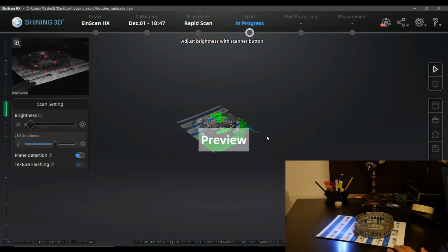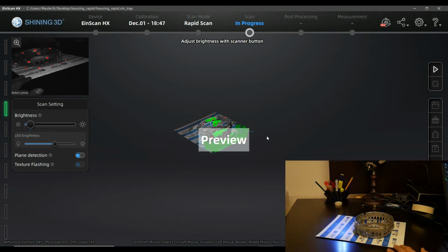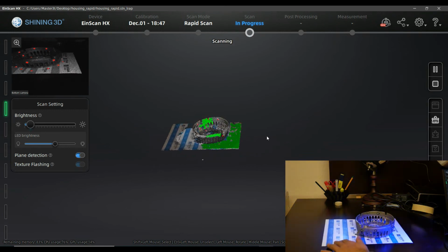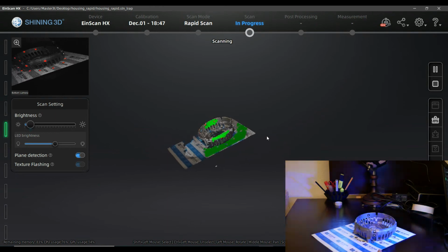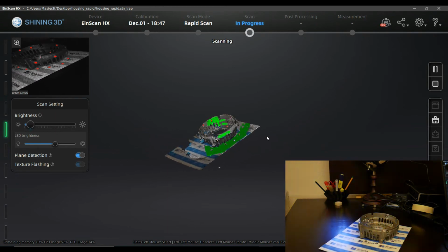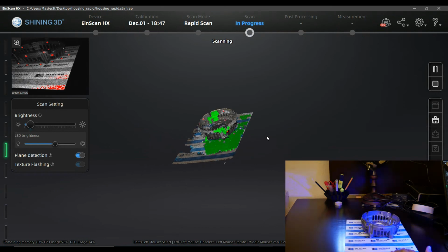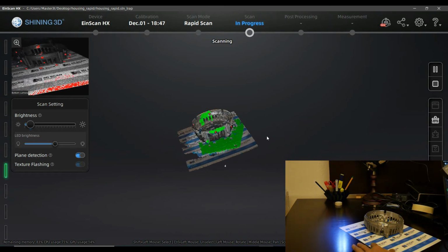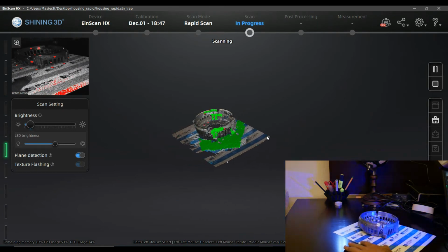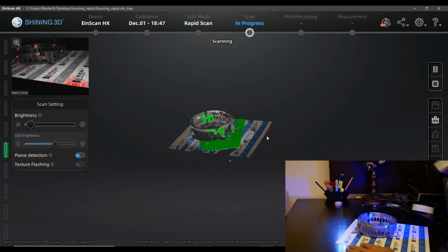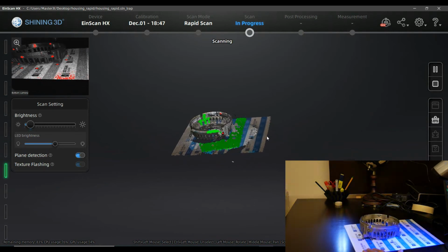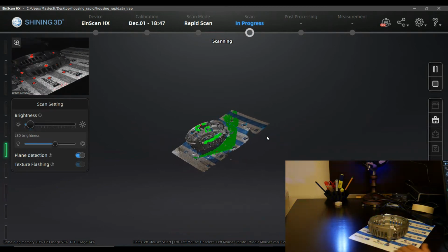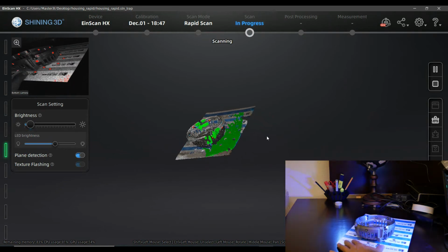I can turn on the scanner again, and you see that over the tracking points it can find its position. So just keep in mind, you sometimes have to change the view, but only if you start to reposition the markers relative to your object. That can mean two things: that you are changing the marker positions on the object itself, or, if you are using environmental markers like on a turntable, or in this case on the foil, they shouldn't be moved either.